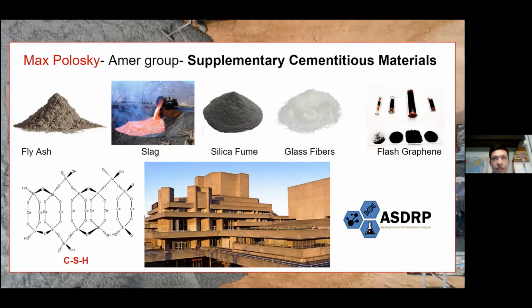It can replace cement in about 5 to 10% weight, and it is also typically added to concrete to decrease the permeability of concrete and overall increase the resistance to corrosion of our concrete, which of course makes it stronger and lasts for longer.